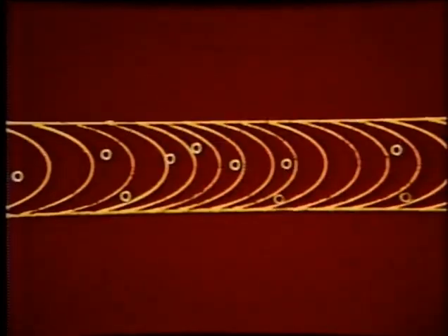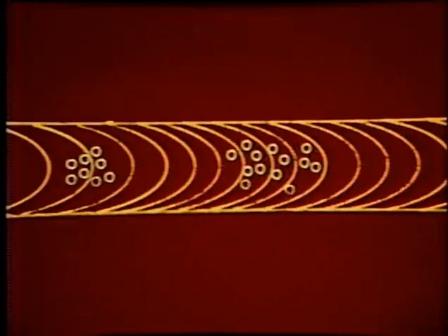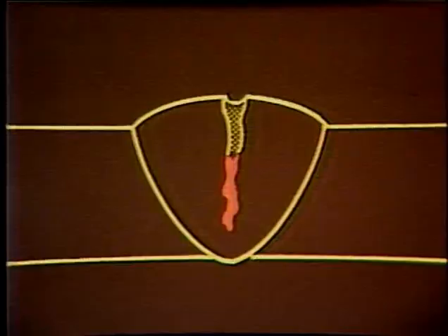For example, uniformly scattered porosity could be caused by moist or dirty base and filler metal, or improper welding technique. Cluster porosity is likely to result from improper arc starting or breaking, or periodic loss of shielding gas coverage. Linear porosity aligns along the boundary of a joint and is directly related to contamination in the base metal, weld metal, or both. Piping porosity results from breaking the arc too suddenly, which allows the puddle to cool too quickly.